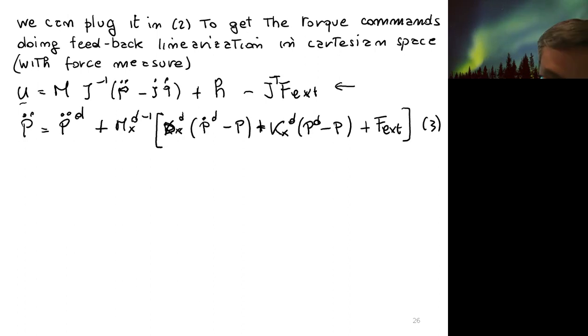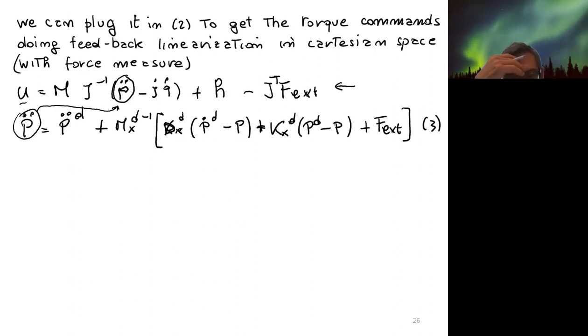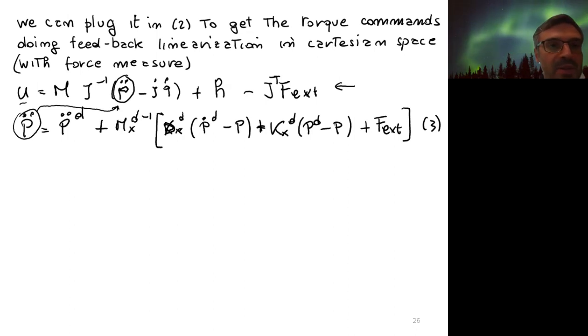with this law, we linearize the system, inverting the dynamics to eliminate whatever is not convenient, and express our system as a double integrator in terms of a new signal that, in the task-based inverse dynamics lecture, we call V. And then we want to apply our desired behavior of the acceleration to the acceleration of this new system, which is simply a set of unitary masses, let's say double integrators, such that these masses behave like an impedance, our desired impedance.